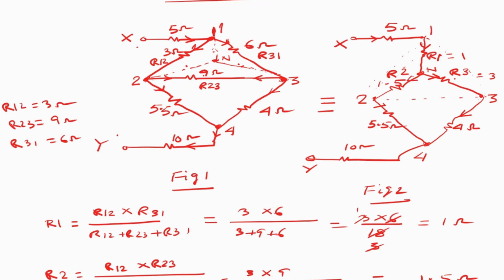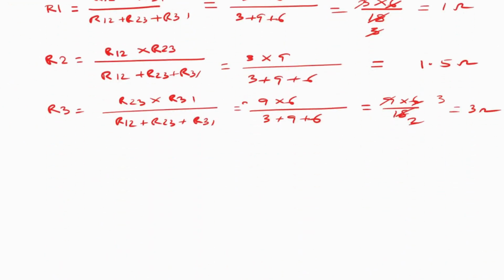After calculating the parallel, you add the 10 ohm resistance, because all the main current passes through the 10 ohm. So the 10 ohms will be in series with the parallel part. So how will you calculate? Now write down the note here, RXY, the equivalent resistance between terminals X and Y.